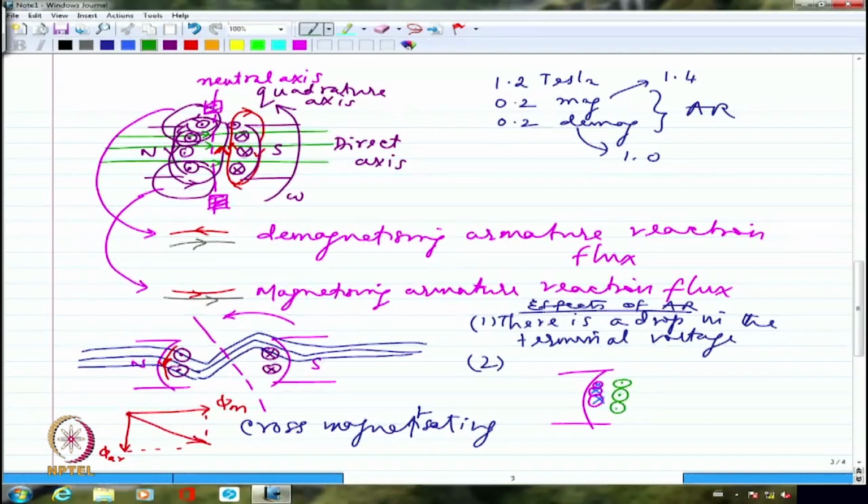So please understand the connection. You are having the armature conductors which are placed in the rotor. The armature conductor connections are brought out through the commutator and brushes. From the brush, the compensating winding will be connected, but in anti-series. So it is probably wound in a particular way, so that it manifests itself with the dot and cross in the opposite sense to that of your armature current.